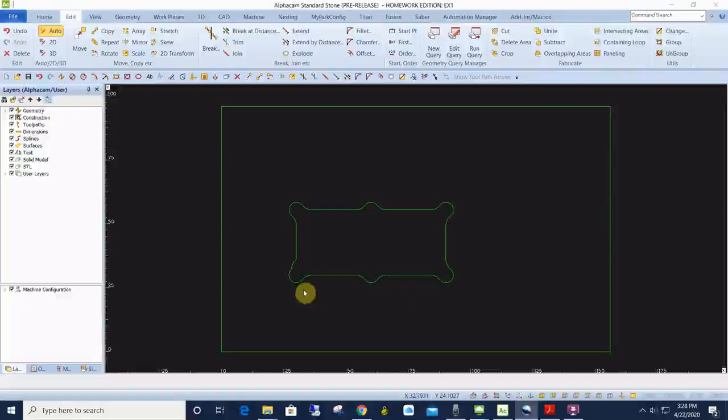Now we'll show you how to do the all function for the fillet. This will put all the fillets automatically on this part all the way around without having to click each individual line and arc. To start, we need to undo all the fillets we previously did. So click each time till all fillets are gone. If you go too far, as in this case, showing a trimming accident here, I went too far. I can hit redo right next to it.